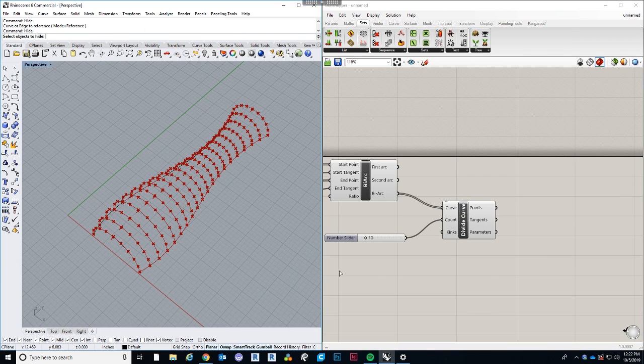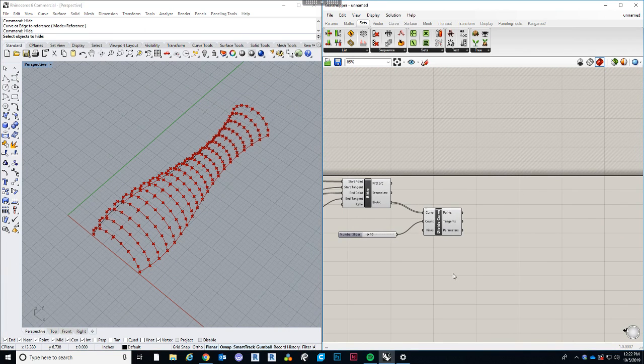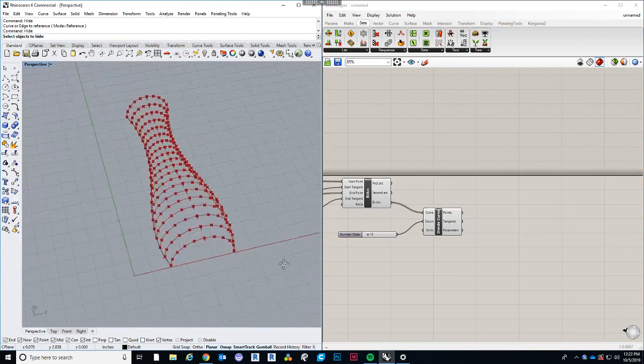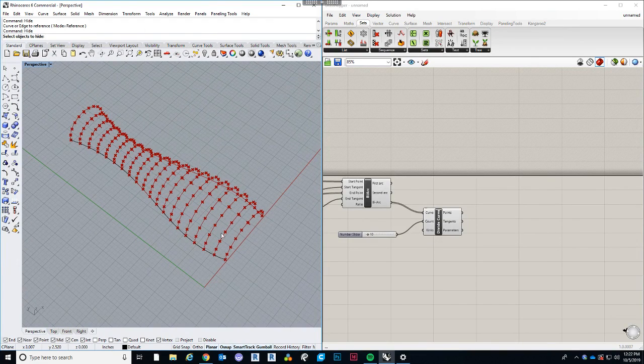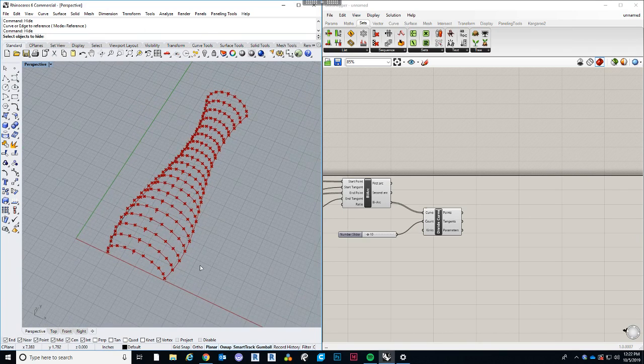So a cull pattern, I think I've gone over it before, but a cull pattern uses a true-false Boolean pattern. It's just a series of either true-false statements. And if it's true, it'll keep that number in the pattern. If it's false, it will remove it. And to start off, we need to extract every other row or curve in this situation.